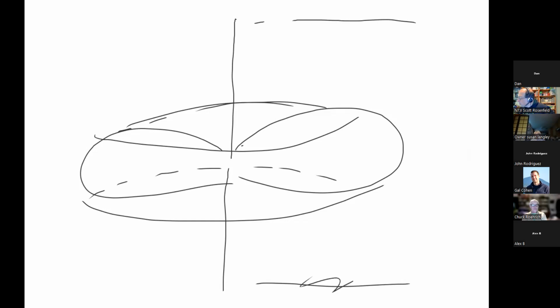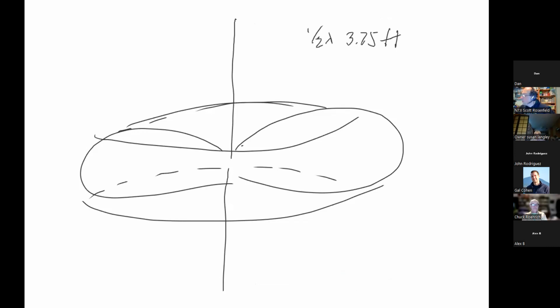So now let's take a look at what we just did. We calculated our wavelength of 3.75 feet. Or sorry, our half wave antenna. So that's the antenna we just came up with, 3.75 feet long. Okay, well, we could actually try to put up a half-wave vertical. Let's say we wanted something on the roof of our car. We could try to put up a half-wave vertical on the roof of the car, but it turns out that a half-wave vertical is actually difficult to feed power into when you're feeding it at the end.